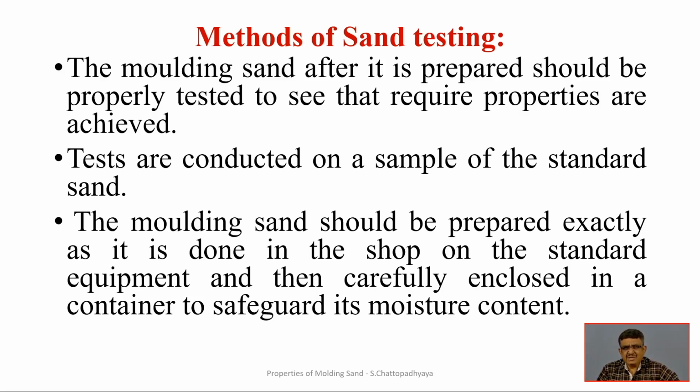And the moulding sand should be prepared exactly as it is done on the shop floor with standard equipment, and then kept carefully in a closed container to safeguard its moisture content. Moisture content is a nightmare for casting people, and it sometimes makes casting very difficult.